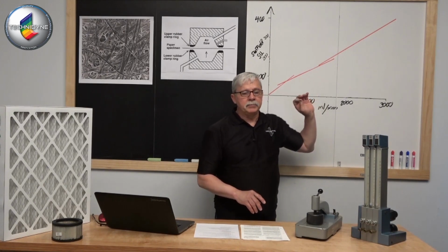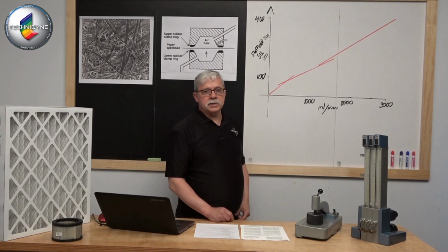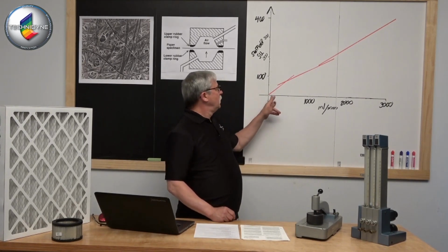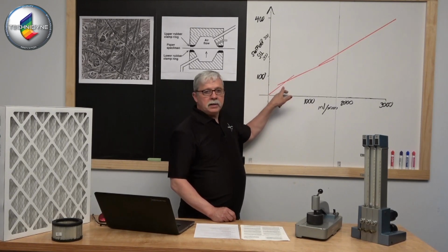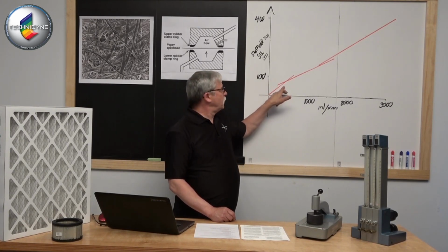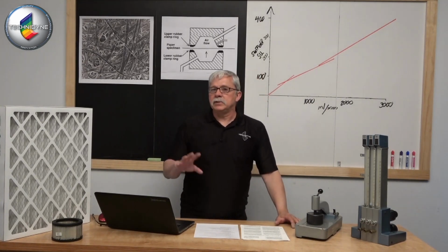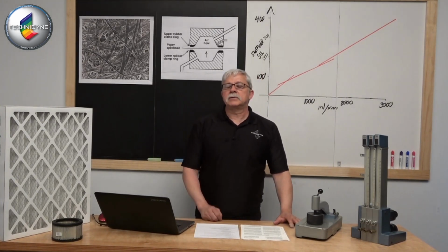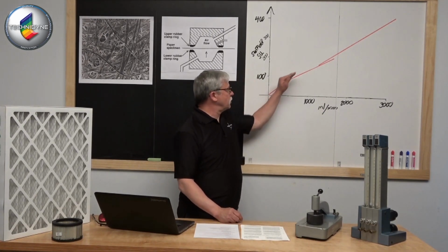And the relationship between the Sheffield unit and milliliters per minute, or engineering units, is like I have in a drawing here behind me. The first tube, 0 to roughly 60 Sheffield units, has a slope that is related here on my first section of my graph. That slope is roughly 6, maybe 6.8 milliliters per minute per Sheffield unit. So there's certainly a slope here.